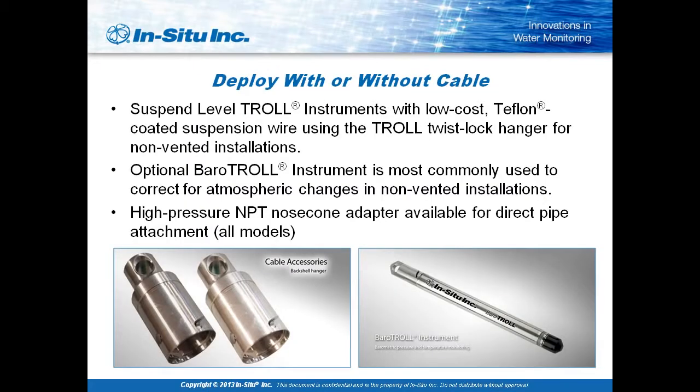If you are using a vented system, there is some maintenance that you have to do that you don't have to do with an absolute system. Basically, you have to keep that vent tube clear and unobstructed. The way that you do this is by using a desiccant.